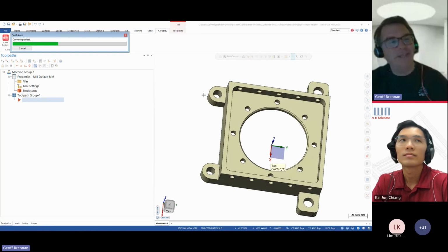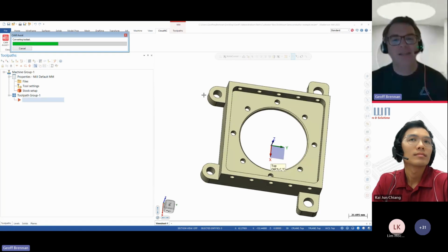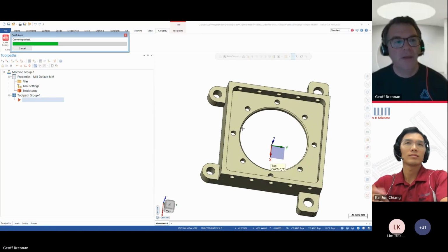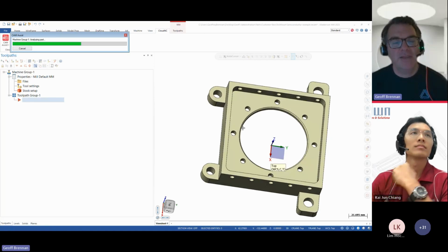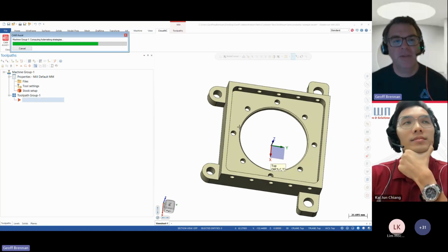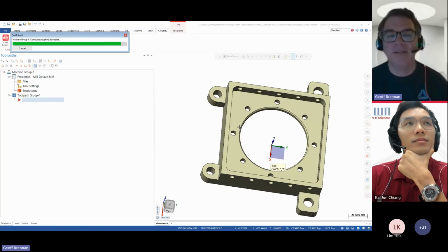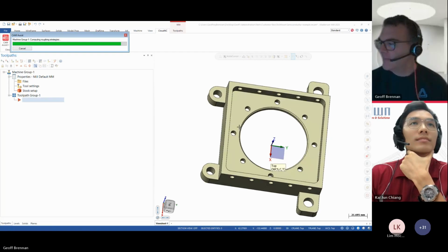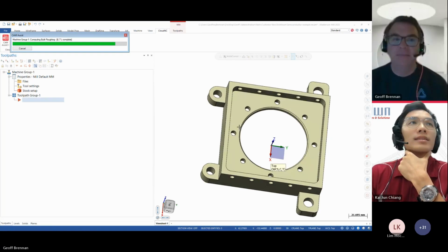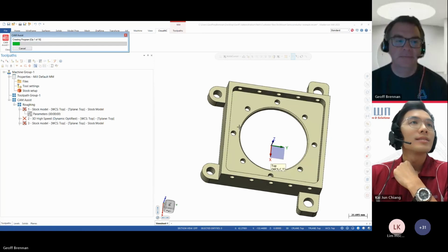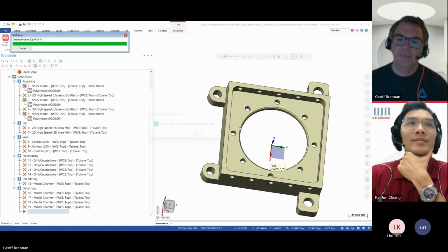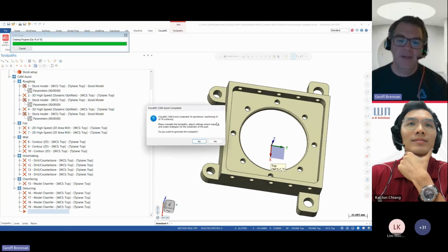So I actually meant to give the stock a little bit more height in Z to account for that, but you'll see that, depending on how we had this set up on the machine, we could probably run this quite safely without defining the stock and bringing in all the devices and things like that into our Mastercam file. I'll say no in this case.